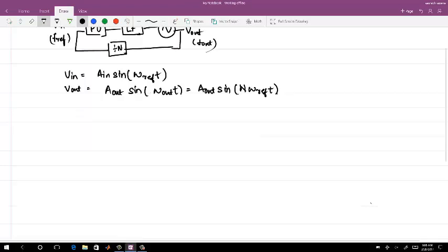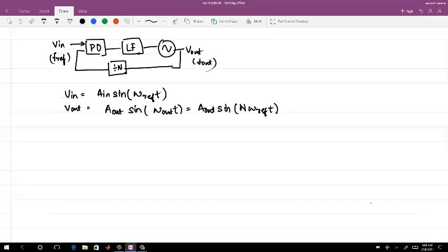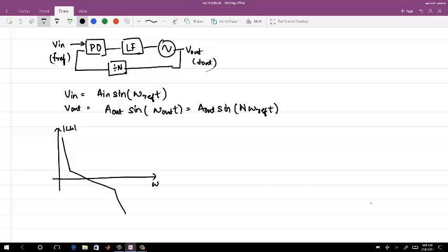When we did all the phase noise analysis, we looked at the loop gain of this loop with respect to omega. For a type 2 order 3, we had something like this. This was the unity gain frequency. You have a zero here and a third pole here.